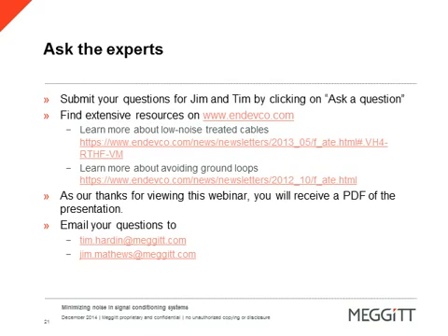Jim, I'll take that one. Okay. For this type, paying attention to the presentation that we had here, I would choose a grounded accelerometer, which is, of course, IEPE, as this person has suggested. And then I would use an isolating mounting stud. Then that is your best shield against electromagnetic and other types of noise. So that gives you one point common ground, which would be the signal conditioner. So the conditioner must be grounded. It cannot be floating.